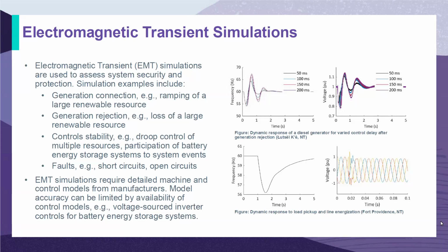And if there's a contingency on the system, so say, for example, the sudden loss of the solar, the sudden loss or the sudden connection of the wind turbine, that's an acceptable event. Can the system remain stable if you do such a thing? That is an event that you might not be able to see on a minute-by-minute basis. So we look at it from a 50 microsecond simulation to shock the system and see if it remains stable under various conditions.